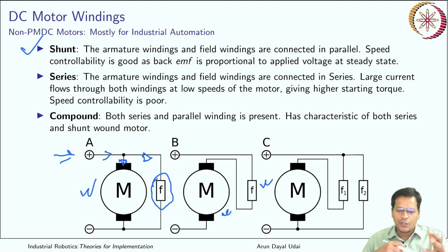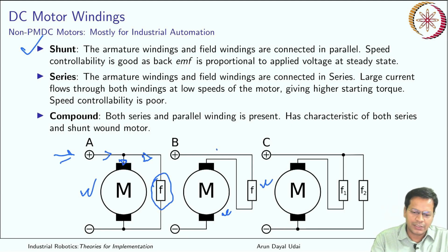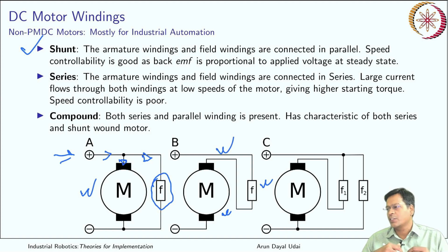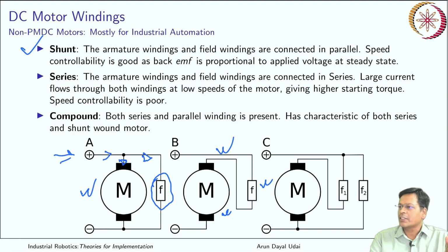Once the rotor takes up the speed, it takes a small amount of current, right? If it is no load, it can draw less current. So this type of characteristic is also useful. Let us say you want a starting motor for your car, where the starting current is required to be very high, but in that case normally a PM DC motor is used.